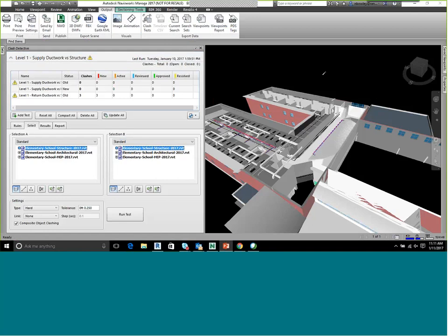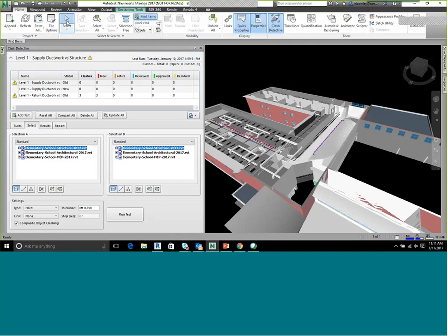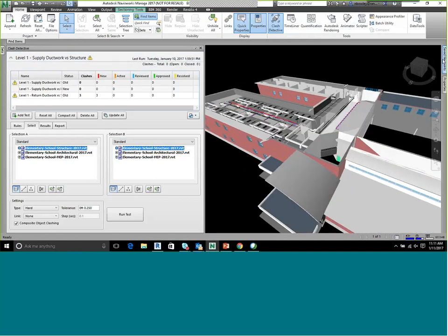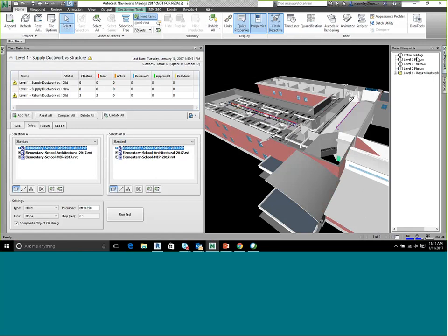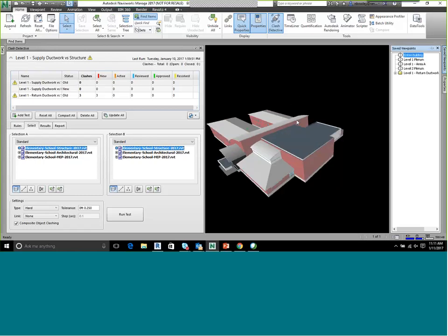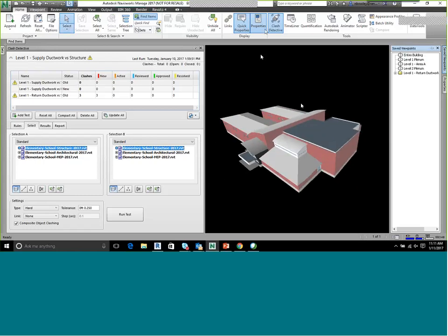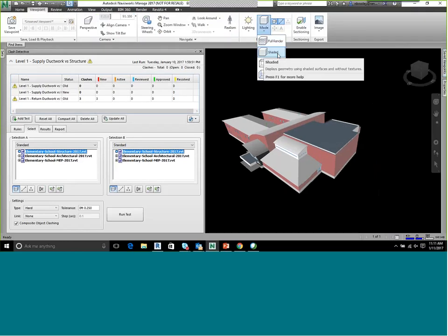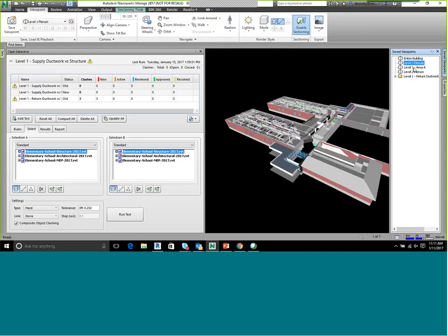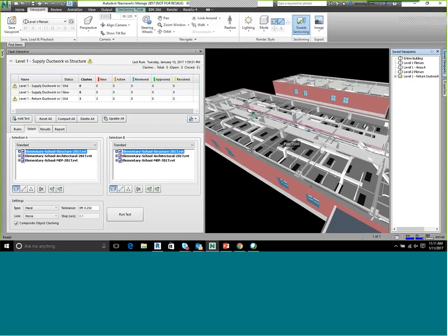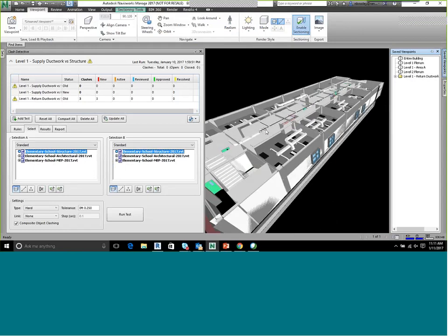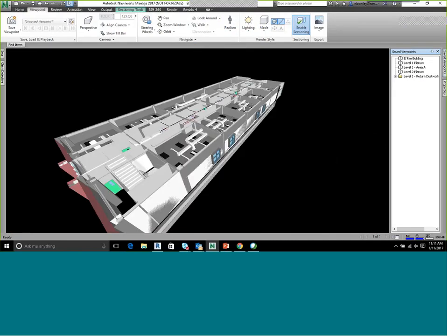Okay, so this isn't an intro to Navisworks class, so I may not go to as much detail as somebody who's maybe never used Navisworks before. But basically, I've appended my Revit model into Navisworks. I had a view created for the entire building. And then for the view properties, I actually like to set it to shaded, and I make sure my lighting's turned on. Setting it to shaded allows me to assign colors to different items. And so we'll go ahead and do that. And let's unpin the Clash Detective Wizard.